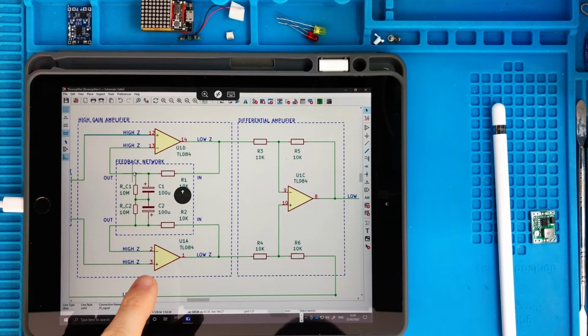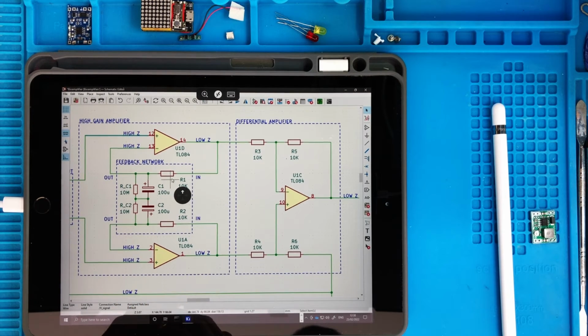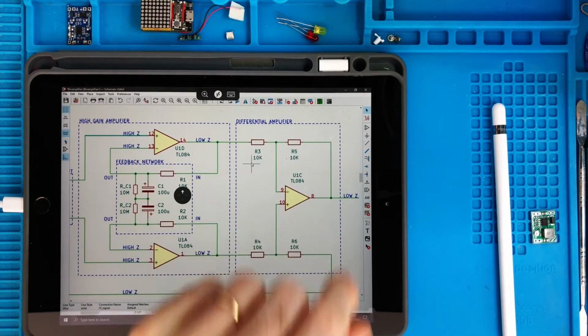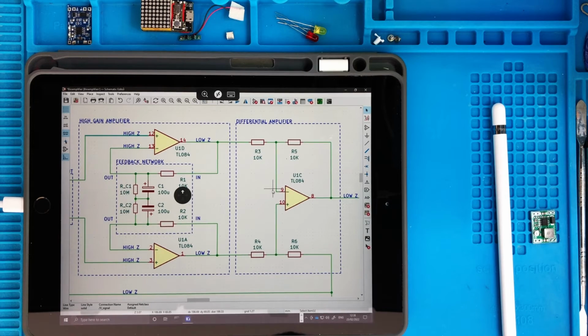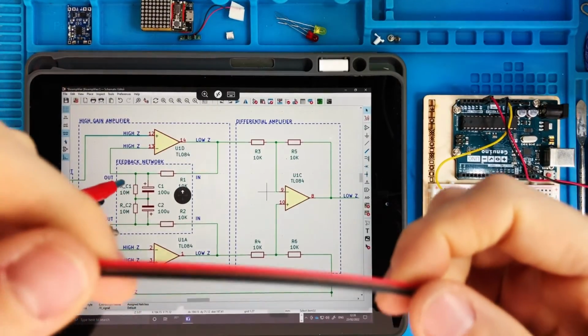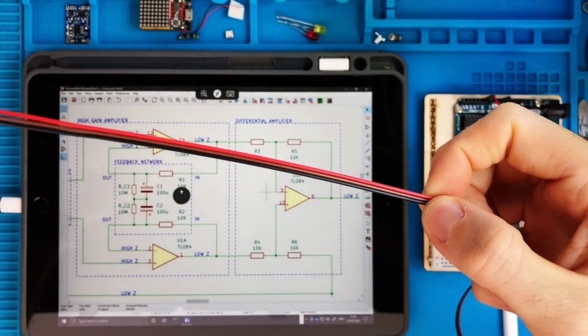And once the signal is amplified, we want to get rid of the noise by making a differential amplifier, which is the second stage here. So if you remember, if you have 2 electrodes having the same type of noise superposed, if you take the difference of the voltage between those 2 electrodes, on the assumption that the noise is the same, you will cancel out the noise. So this is the beauty of having the differential amplifier. So what can try to guarantee this condition in our case? The fact that the wires we are using are very close to each other.